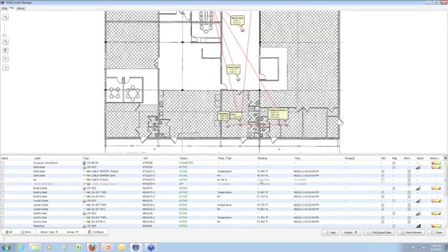And what type of batteries do we use? That's actually an excellent question. When these are battery operated, so when they're just working as a node and not a repeater, we use 3 standard AAA batteries, and basically it's spec'd out at a 15-minute recording interval. It can last for about a year in the field.